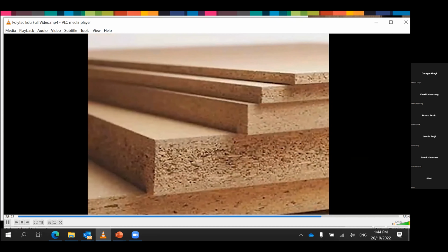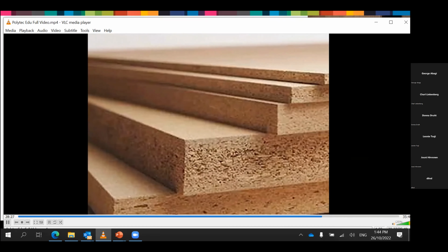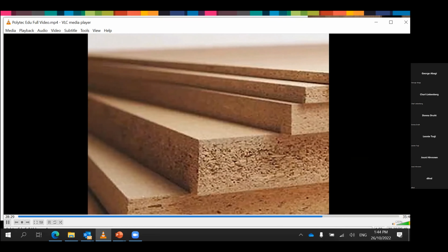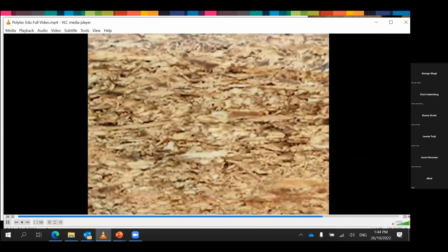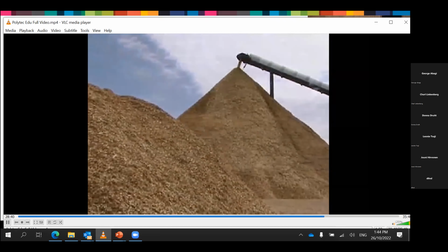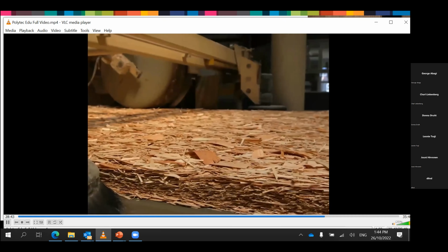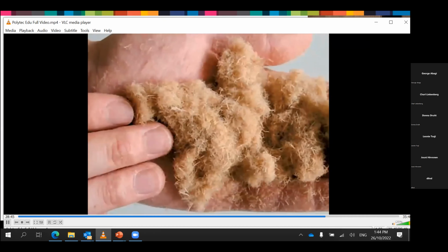Particle board is produced in a similar process to MDF. In both products, the same wood, Pinus radiata, and resin is used. However, wood fibres in particle board are bigger than MDF, and therefore less dust is generated when cutting. Another important factor that should be understood is the interlocking of the larger wood chips in particle board, rather than the fine wood fibre of MDF.